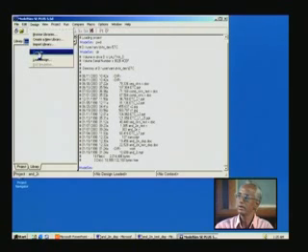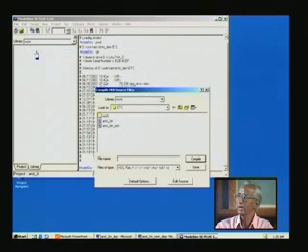do the compilation. So design, compile we have given, and then a menu popped up. In that it lists .v files here. So you can see all .v files are listed here. And now what we want is, we had a test bench as well as a design, and if we remember, we have already included the design file in the test bench.